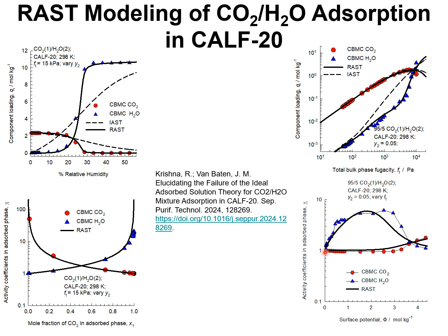In other words, the activity coefficient models should not only respect the limiting values at either end of the adsorbed phase mixture compositions, but also they should respect the fact that at low pore occupancies in the Henry regime, both activity coefficients should tend to unity.